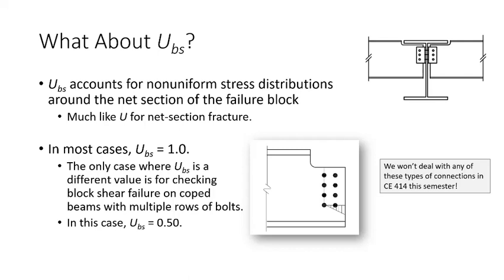Well, I can't just connect those directly if I want the floor surface to be flat. So what I'll do near the end of the beam is cut a little bit out of the top so that I can stick the beams together and frame them together. That's called coping, okay? We do that in steel frame construction so that when beams frame into girders, the